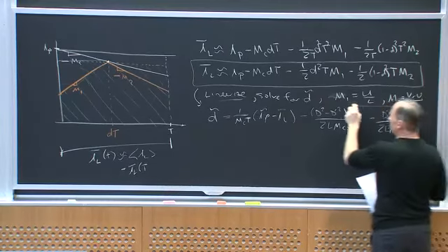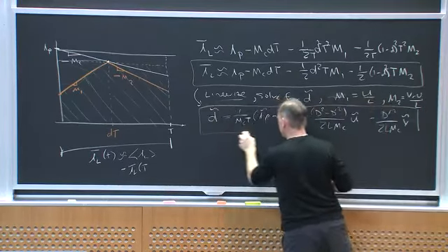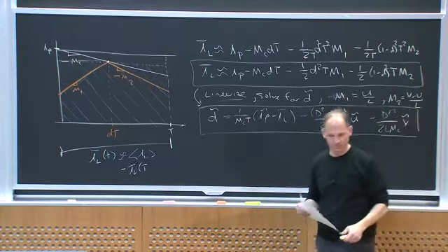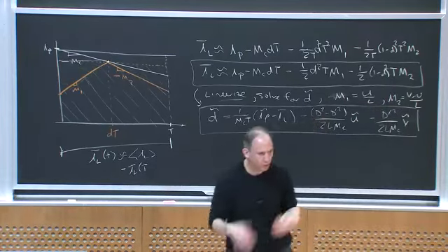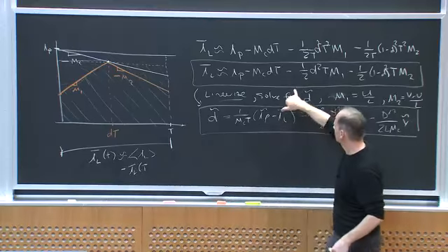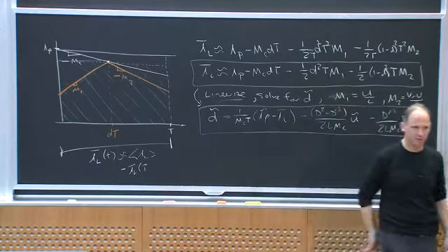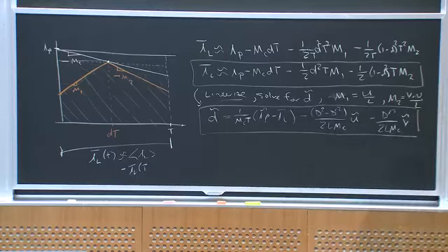So this is a linearized version of this for the boost converter. If you wanted to do a buck-boost converter, you'd need different expressions for M1 and M2, and you do the same process and linearize it, and you get a different expression. Any questions about that?